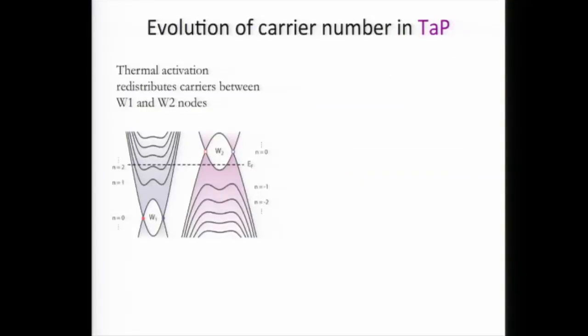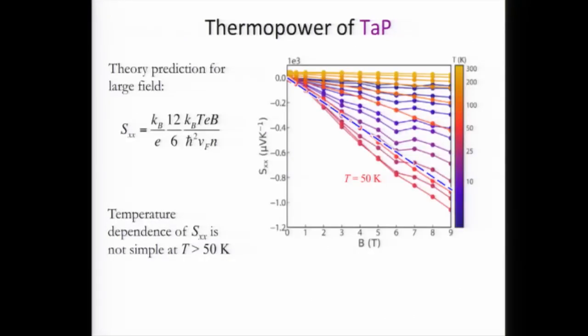That's not bad at all, because the commercial problem is you take the old-fashioned thermoelectrics and you want them to cool some detector, and the colder it gets, the more sensitive it gets. And the old ones tend to die at around 100 K or higher than that, which is a big problem. So in a sense, this might all be good in the end for low temperature thermoelectric cooling, which might be a big deal.